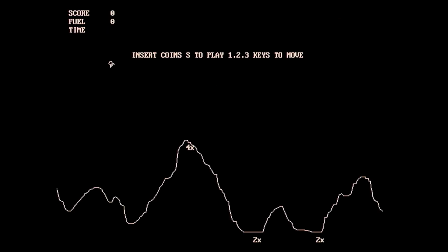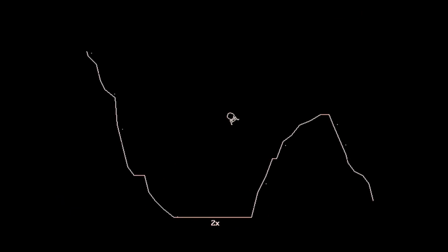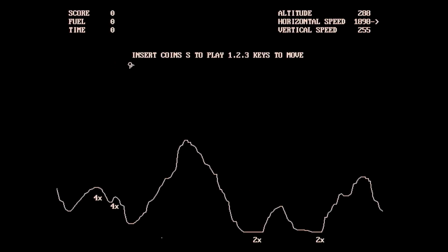But I wanted to show you that I've managed to eliminate the majority of the snow, and this is the same sort of interference that the IBM CGA color graphics card would experience. So it's certainly possible to eliminate the snow for two of the main graphics modes. Just the high color mode in this particular case I wasn't able to do. That in fact wasn't one of the original CGA color modes, it was actually an extended mode in the MCGA card, which came out I think with the IBM PS/2 Model 30.